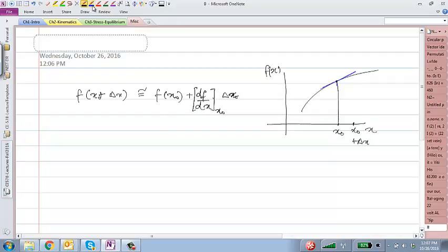But that does not mean that the value on this side of this point and the value on the other side of the point in terms of tractions would be in the opposite direction but the same magnitude. Even though the value to the left and the right of that point is the same, the slope at that point is not zero. It's the slope, the derivative of the stress, that is what we are talking about.